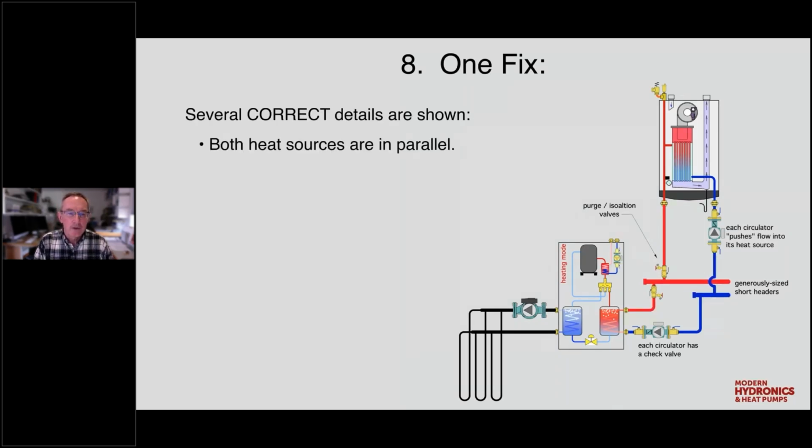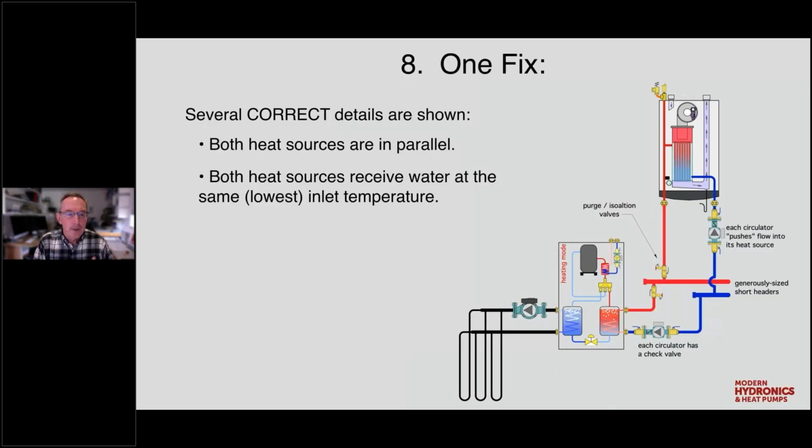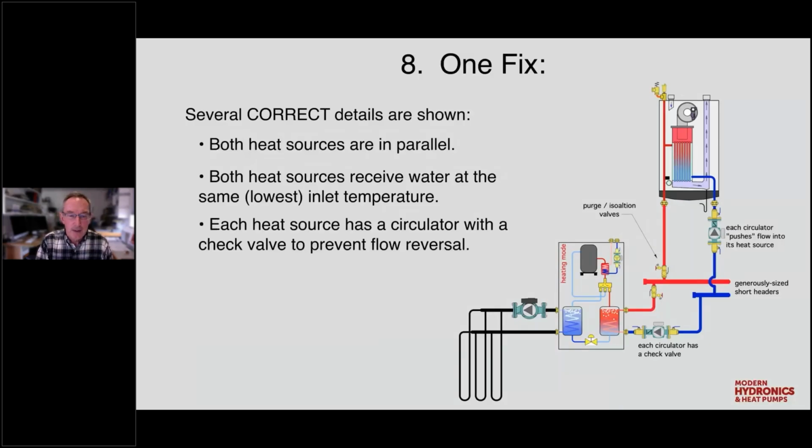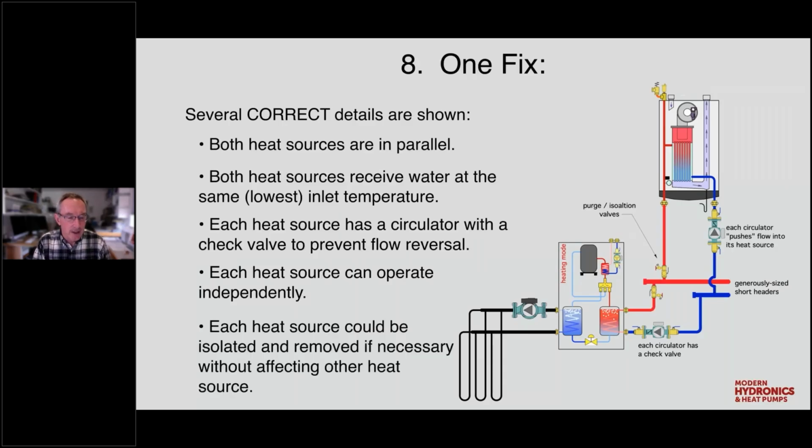Okay. So again, they're in parallel. Both receive the same low temperature water. So you're going to have the best efficiency on both of them. We talk about the check valve. Each of them can operate independently or they can operate together. And each of them could be isolated. And if necessary, they could be removed for service without taking the other heat source out of operation.